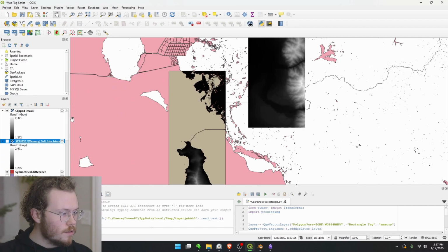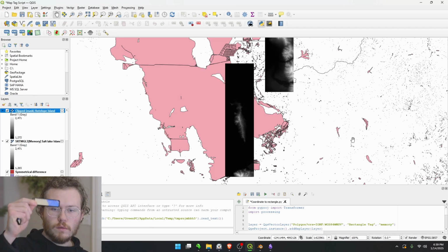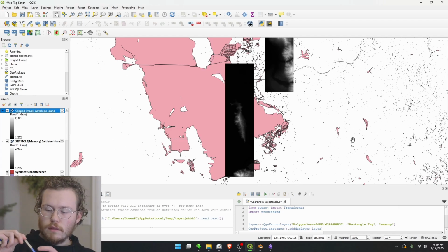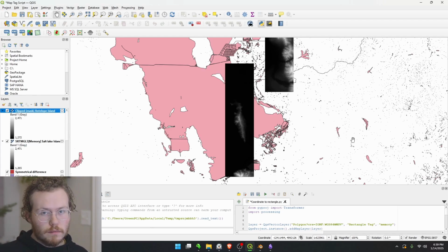So nice. One thing I'm going to do before we export these to STL files is add an offset to the elevation on each of these maps. The reason is that for maps like this one with Florida, the elevation difference between the land and the sea is nearly zero, so maps like this would be hard to see because of that lack of difference. So I'm going to add 500 meters vertically to all of the terrain.